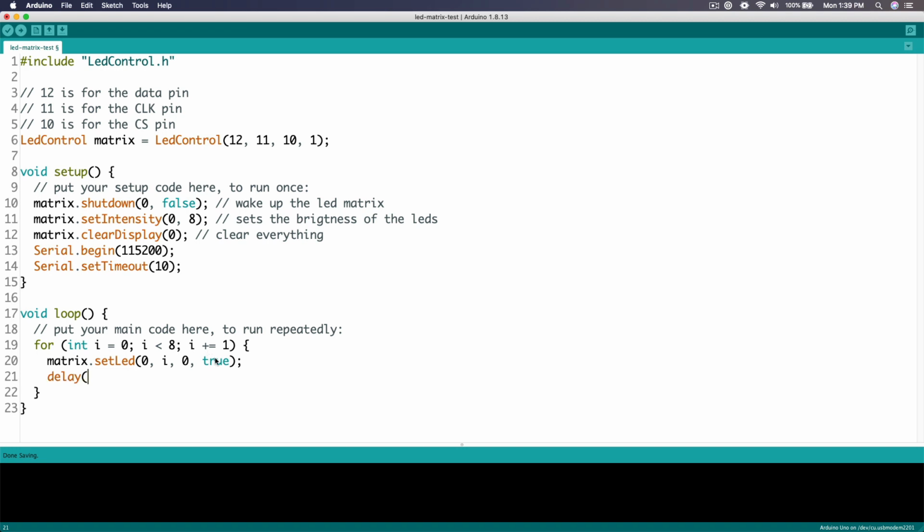And we're going to add a delay of 2000. We're also going to print here with Serial.println. We're going to print basically this, plus i, and we have to turn this i into a string. Right now it's a number, so we can create the rest of our string. We're going to print basically what we're sending to the Arduino to make this happen.